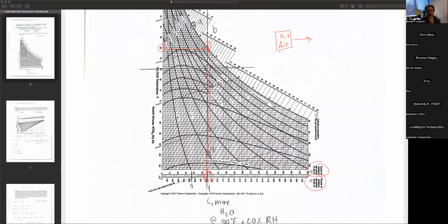So in this case, it would make sense that the wet bulb should be this way. When I was talking through this a moment ago, I said 60 and 55, and I think 60 and 55 is higher than 70% relative humidity. So I think it has to be this one here, which is 80%, which makes more sense, because I would expect the dry bulb and wet bulb to be closer in temperature in that case.